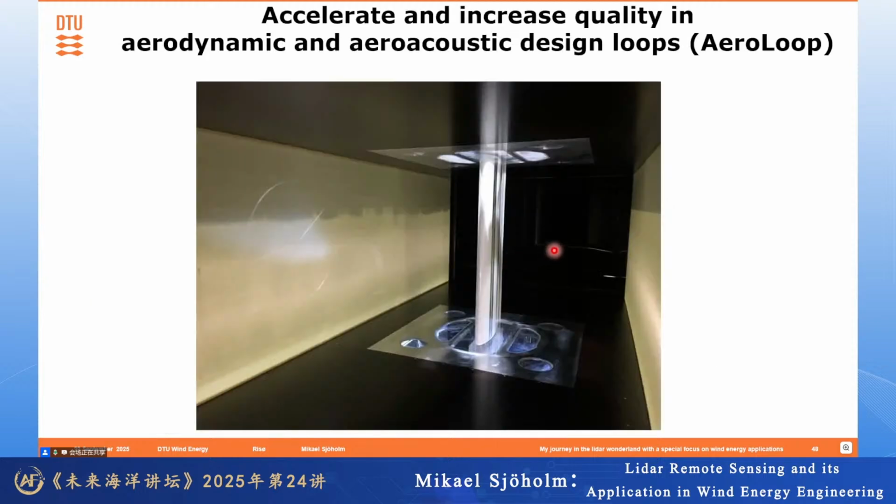You can see here is a cross section. It's basically made for testing blades of wind turbines at high speeds, so we can produce up to 105 meters per second wind. And it's also an acoustic wind tunnel where they can shift the normal walls into some Kevlar mesh that lets the sound through, and they can measure the sound outside of the wind tunnel.